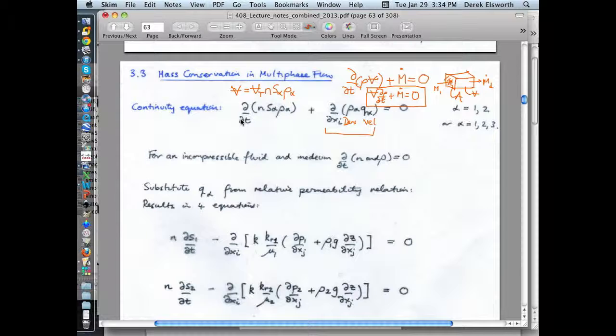So that's all I'm going to say about that. But it's the basic basis of any kind of multi-phase flow problem, is that if you can define this conservation of mass as a function of the porosity, the saturation, the density of the fluid, and the flow rate at which the fluid is going into the upstream portion or out of the downstream portion, this is Darcy's law, right?